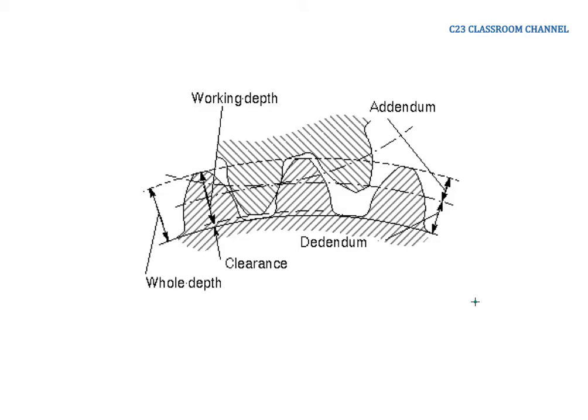The idea here is that the volume will be trapped into this space. And then when the gear pushes into this area, it actually squeezes the fluid to the other component. So the basic idea is we transfer the volume by pressing the liquid here and moving it to another volume, to another area.